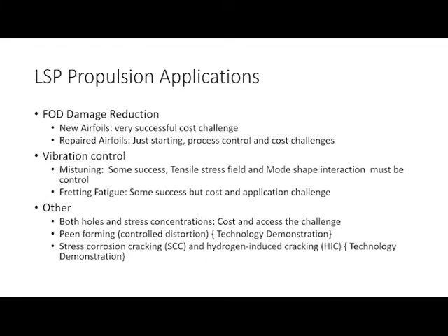And so when you machine, you're obviously machining into an area that was previously residually stressed. What the military is currently doing is, by and large, replacing most airfoils where the damage area is great enough in the LSP area, and not going in and blending it, because the question is: when I did that blending, how much of the residual stress did I lose?